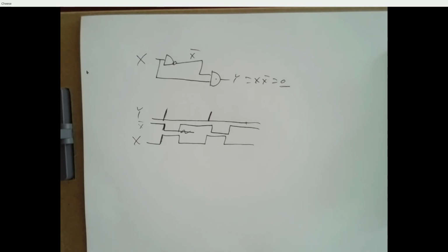These are timing issues that you have to deal with when you have signals coming from different places feeding into a circuit. And this is going to take us to talk about something called a flip-flop. And a flip-flop is a glitch-free way to do memory, and it's what we build all of our systems out of. And then we're going to talk about different types of flip-flops, and this will include a D, a JK, and a T. So we'll learn 3 types of flip-flops.